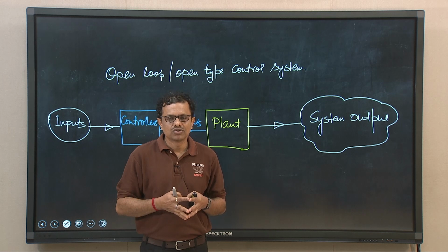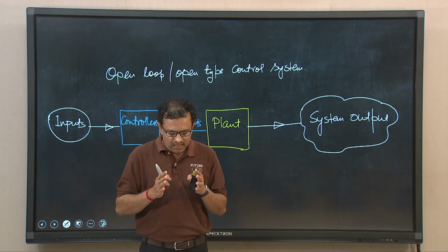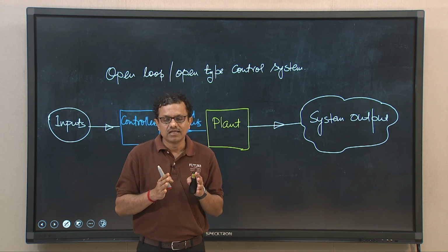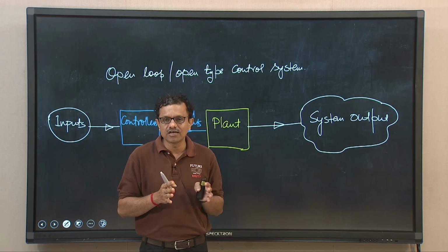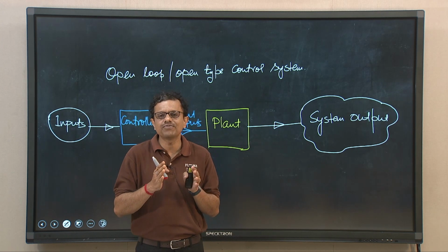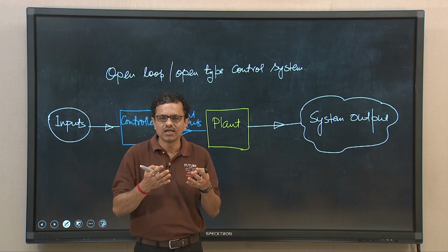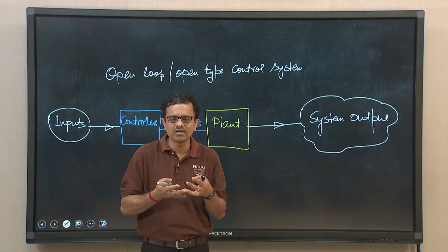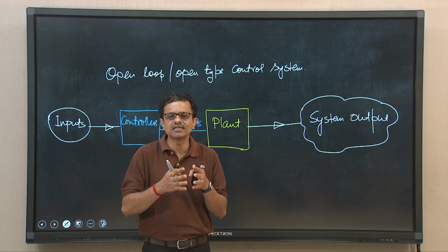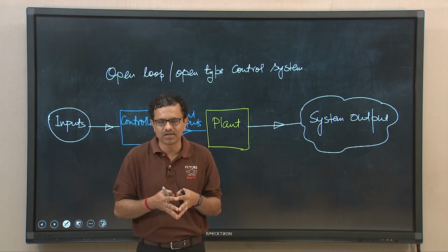The electronic control unit for this type of system is not correcting the air fuel ratio. As I said, if the car needs to go uphill, certainly it will decelerate. So, the speed won't be 50 km per hour, but if we need to maintain the same speed, we need to supply an additional amount of air fuel mixture to the combustion chamber, right.